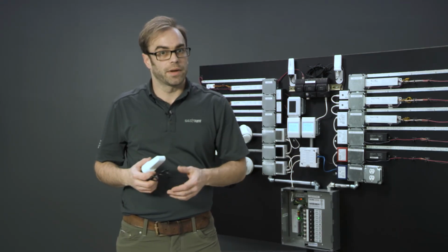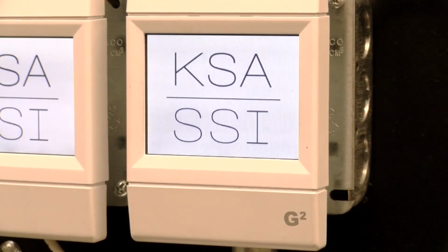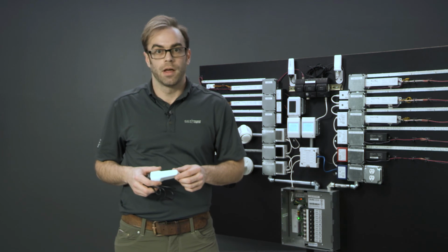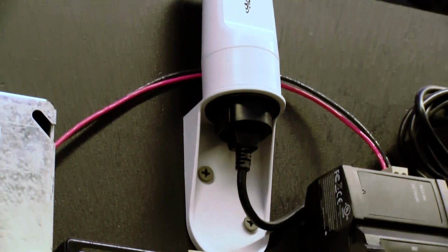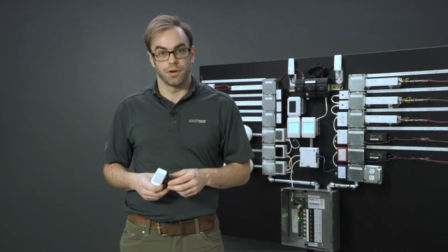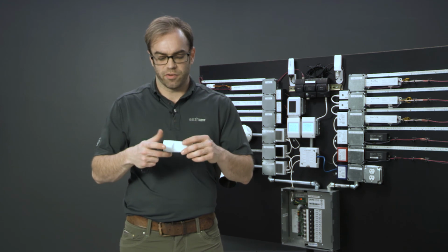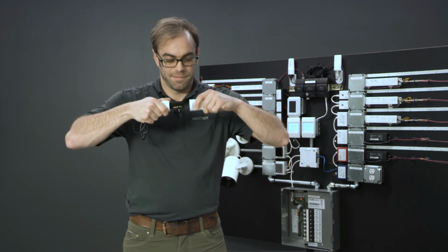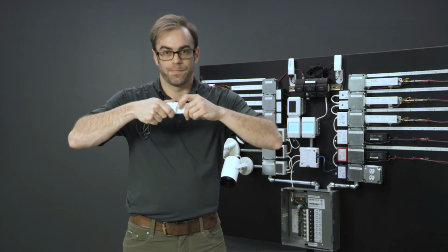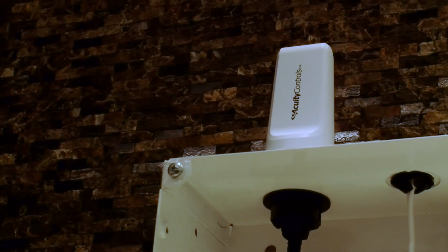It should contain the following items within its enclosure: Wi-Fi antenna, a GFX G2, and a PS150. The PS150 will power the GFX G2. The Wi-Fi antenna allows for wireless interfacing with the controller for programming purposes. Take care when installing the Wi-Fi antenna. It's fragile. Pull, do not twist. You can mount the Wi-Fi antenna right onto the enclosure through one of the knockouts.